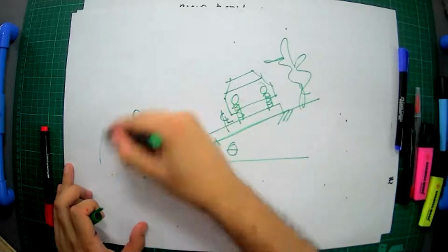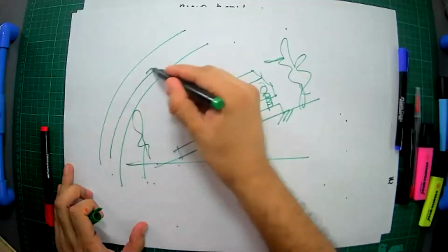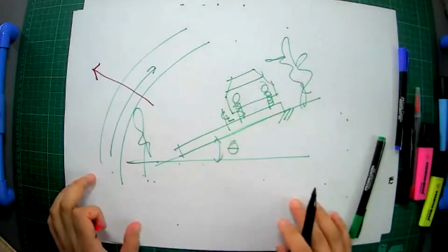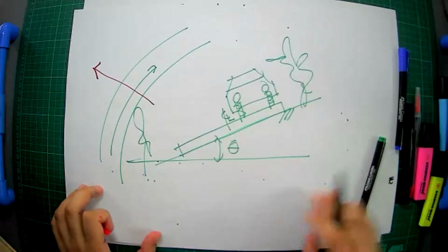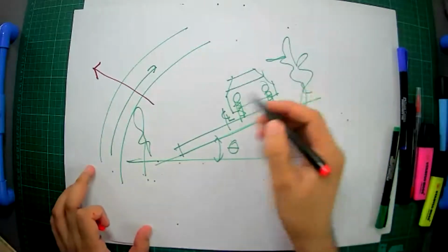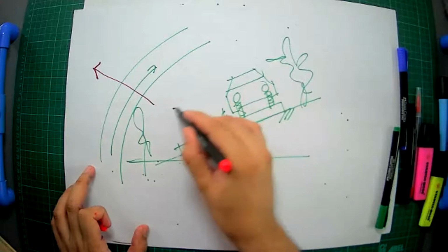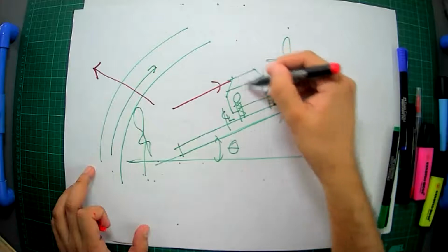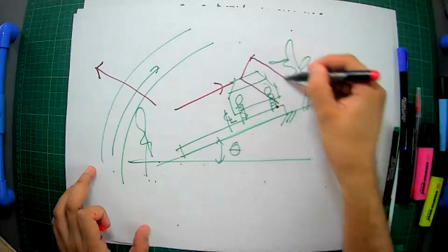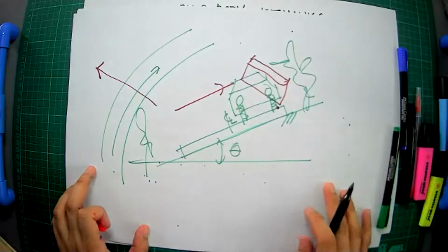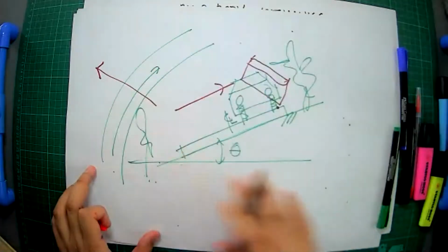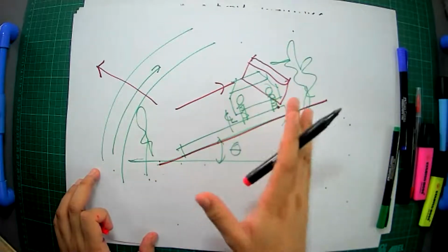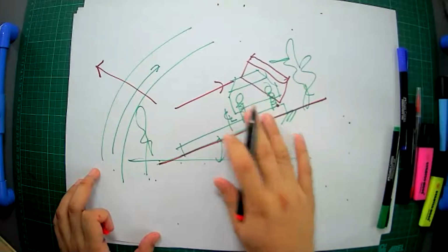So, when you go fast on a curve, highway or racetrack, there's a tendency that you get pushed outward due to what force? Centrifugal or centripetal. You review that, okay? There's a tendency that it will slide, or the worst, overturn. It will tip somewhere here. Your vehicle will overturn, or you will get into an accident. So in this study, we need to bank the highway. We need to somehow super elevate or incline the highway so that we can prevent the vehicle from overturning.